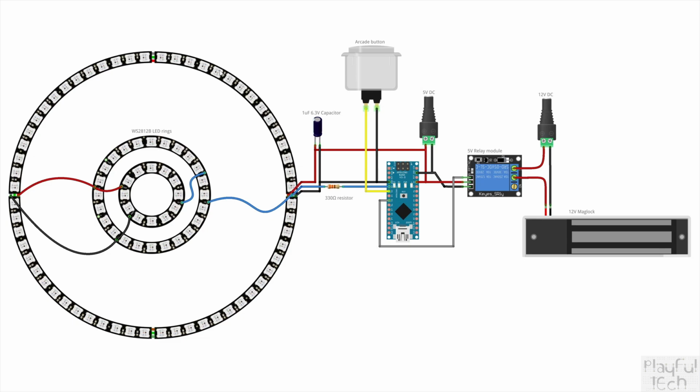These LEDs can draw a surprising amount of power. Each one of these LEDs has a red, a green and a blue component. So if you light all 3 RGB values up to full intensity, they draw about 20 milliamps each, so that's 60 milliamps for just one LED. Now, depending on the sort of light pattern you're trying to display, your total power requirements are going to be slightly different.